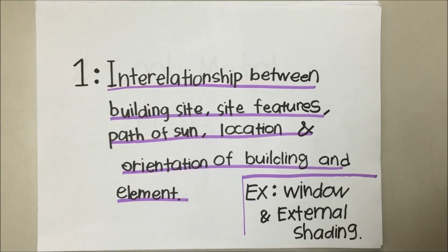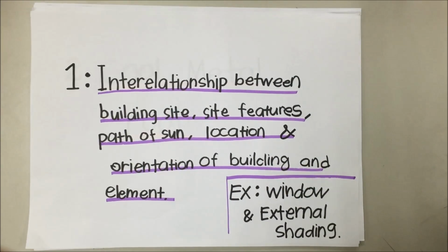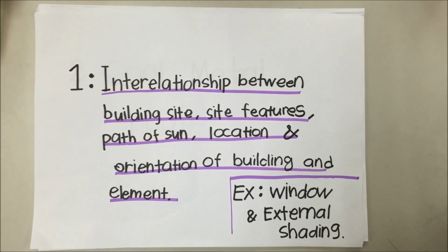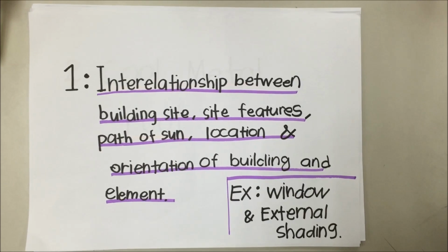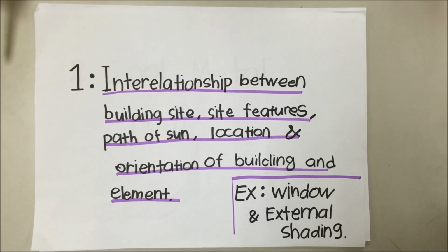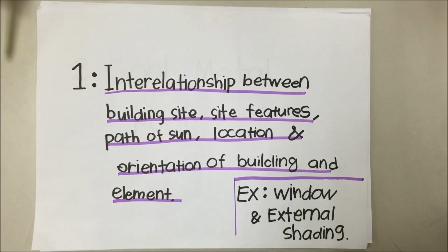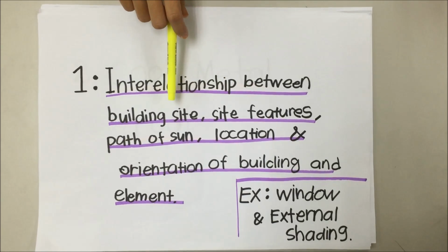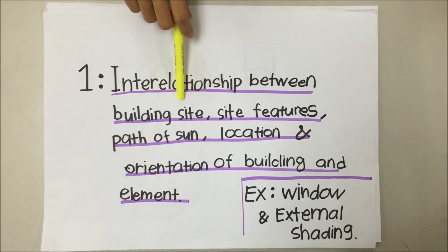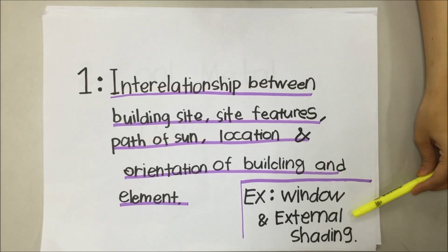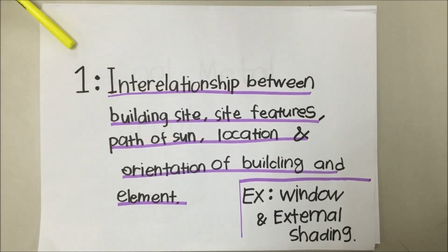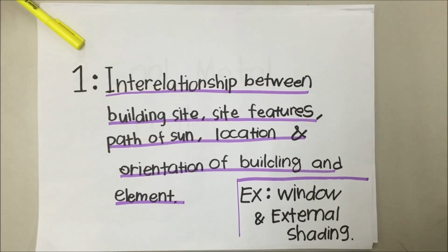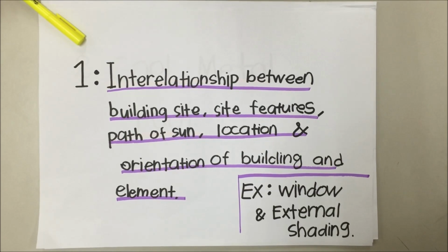Application of a green building in IDP. Green building is not just a matter of assembling a collection of the latest green technologies or materials. Rather, it is a process in which every element of the design is first optimized, and then the impact and interrelationship of various different elements and systems are considered. For example, window and external shading device. These two elements affect direct solar loads and overall energy performance for the life of the building if this issue is not considered early in the design process.